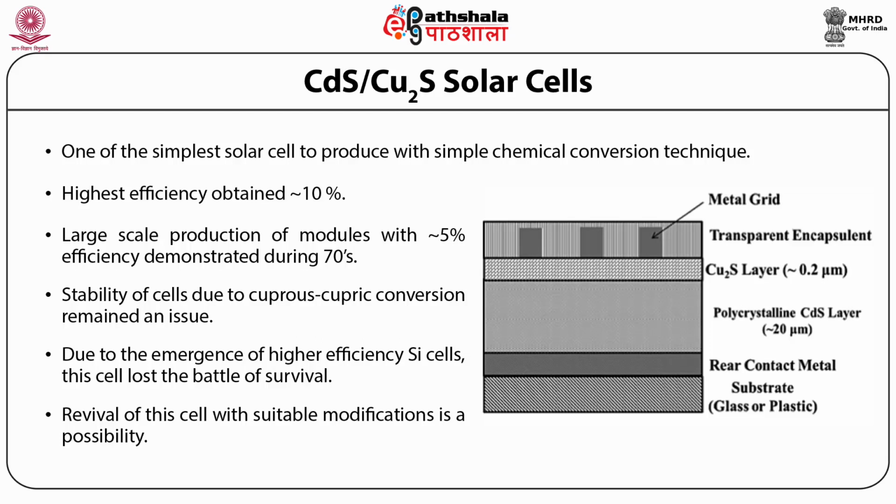Generally, the cadmium sulphide cells are developed by the process called the Clevite process, where the cadmium sulphide is vacuum evaporated onto a metal sheet or metal-covered glass, where it gets deposited to a thickness of only 20 microns or so, as shown in the figure also.